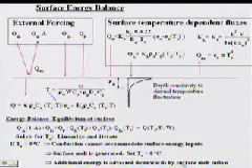So if we get from this solution a temperature greater than 0, we just set the temperature equal to 0, and the additional energy is vectored downwards, and it's just added to the total energy of the snowpack, because we're not worrying about where the energy is within the snowpack. So it was that sort of device that allowed us to keep a single layer model and represent the insulating properties of snow.